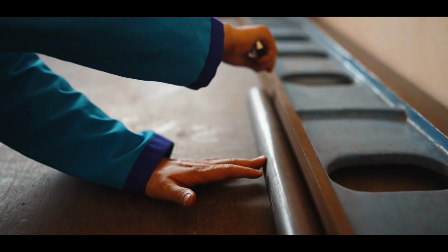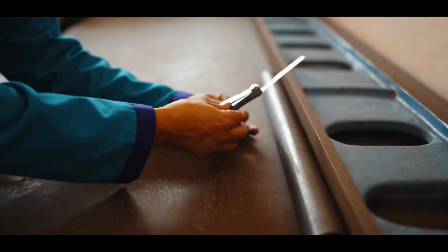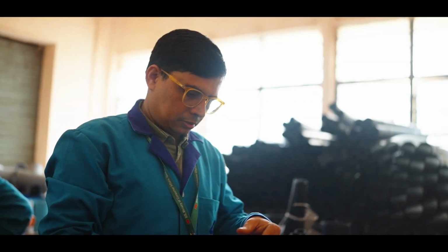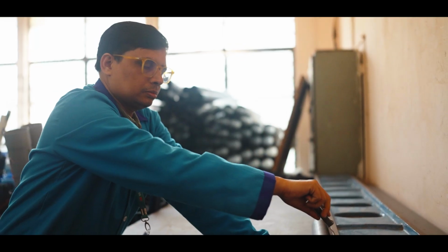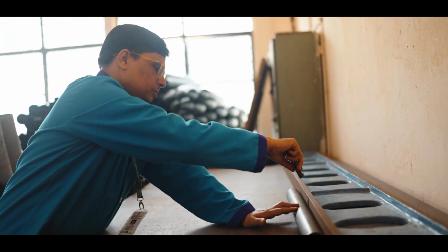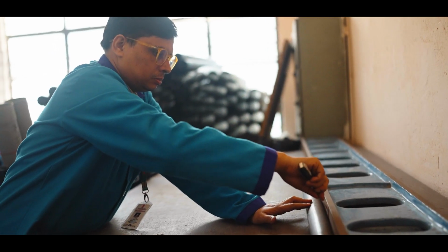For measuring straightness, place the hollow section on a horizontal surface with one side at one end pressed flat against the surface. At the opposite end of the hollow section, determine the difference V in the height of the two lower corners from a horizontal surface using feeler gauges.